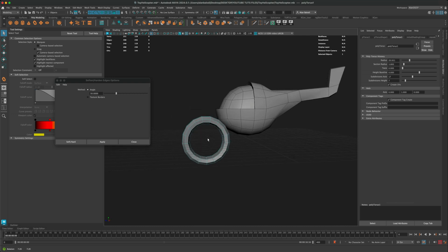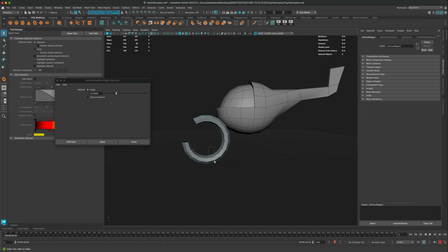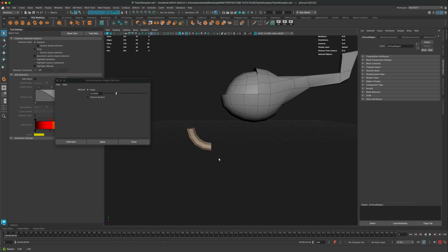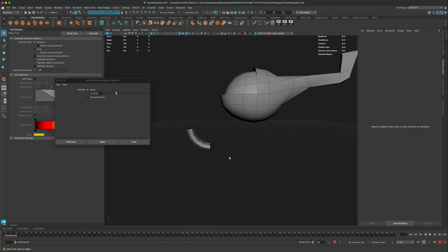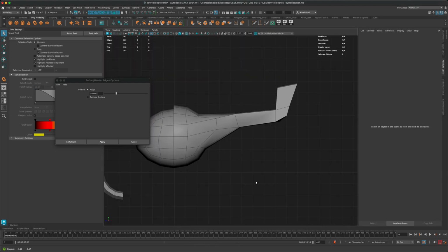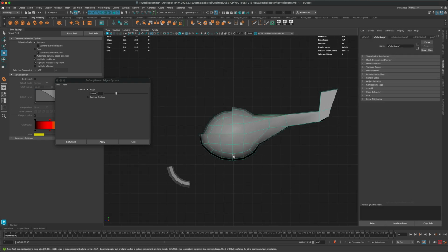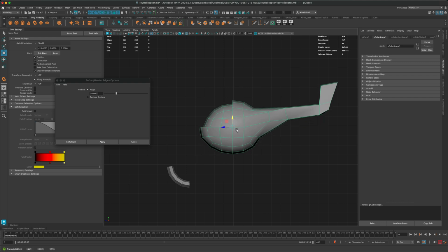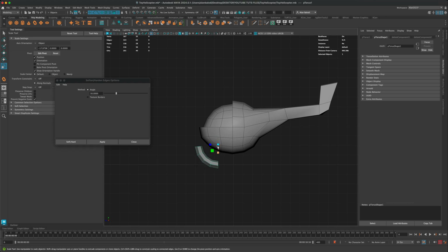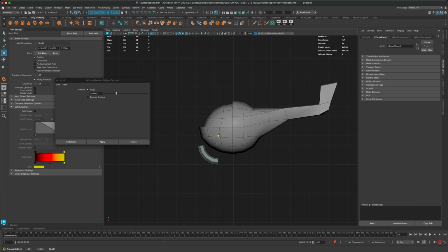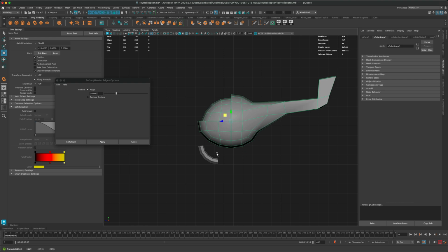All right. I'm going to select these faces here and just delete. And maybe let's go ahead and select all of these, delete, double click, delete. And now I'm left with this. All right, from this, I can go into my side view. And I can see that this line right here is kind of the ground, right? So I would like to move my helicopter up a little bit so I have room for the legs. Let's go ahead and get this into position. So maybe it's a little smaller, but something like this should work.